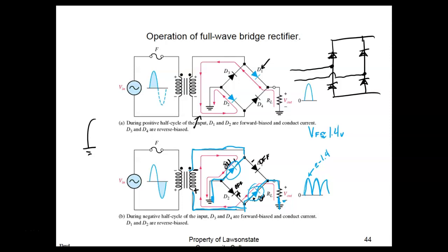In fact, we'll probably break the trainer apart and look at the schematic. When they designate that and then paint it on the circuit card, it makes it easier to find these parts, because a schematic is going to show you the smallest way possible in the logical operation of the circuit. But when an engineer is trying to put these components on a printed circuit board, they're concerned with crossing wires.